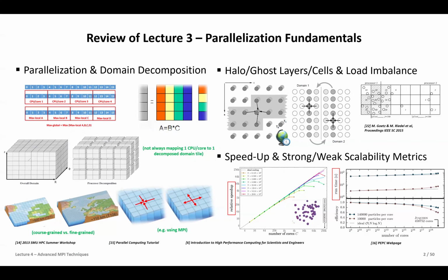In order to have space for it, the domain has some ghost cells that are not really in these nice, beautiful pictures, right? These are more conceptual, that you see here, also for the online audience with a red button, sorry, that you see here. These are basically not existing parts of the domains. These are just memory placeholders to get the interaction going, which is the real value of the domain calculated here. It enables us, and you see this beautifully here, that we can actually simulate across the domain, right? Because at the end of every time step, I would exchange the information.